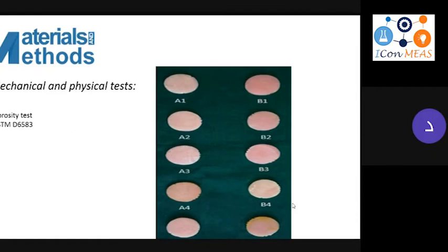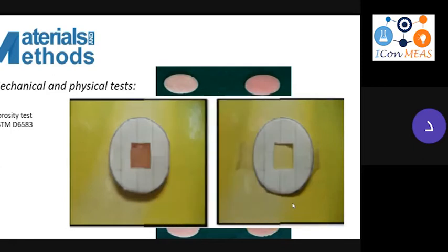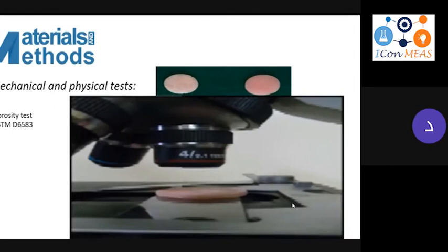Disc-like samples were soaked in a liquid of black long-lasting ink for 30 minutes. Then, an area of 1 square centimeter was delineated at the center of each sample and detected with an ordinary light microscope, and the number of pores filled with ink was calculated.